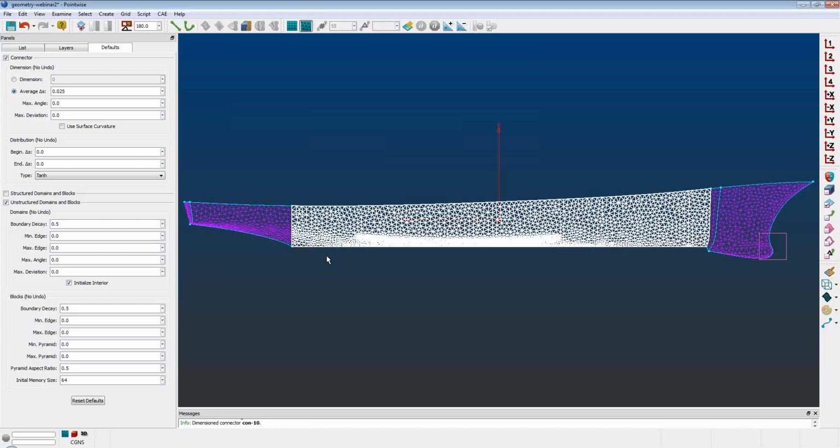Okay. So the ordering shouldn't matter, but the naming does. Is that right? I believe so. Rick, am I correct in that understanding? Yeah, the one place where the order might make a difference is if you're reading in entities from an IGES file and they don't have the IGES name entity, so they're not named. Then they'll get a default name when they're imported that depends on the order that they come in. So in that specific case, if you're reading in geometry that doesn't already have names, the names will depend upon the order that they're read.